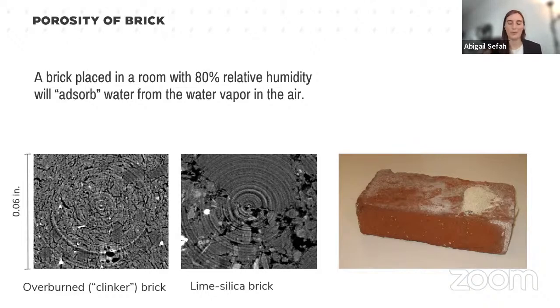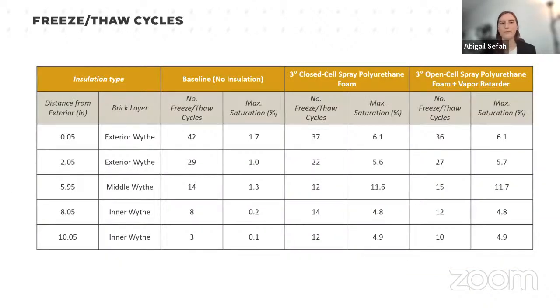And if you put that brick outside in the cold and it drops below freezing, all those tiny water droplets will freeze and expand. And we generally say that if more than 80% of the pores in the brick are full of water, so if it's over 80% saturated, then we would expect there to be damage if the brick were to freeze and then thaw. And that's what we refer to as freeze-thaw damage. For this project, that's where our main concern lay.